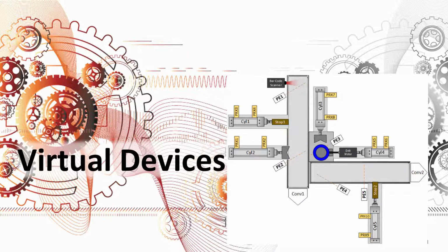Well, if you consider that behavior, that means you energize a solenoid, and after a period of time the cylinder is either extended or retracted. And we know it's extended or retracted, either by virtue of a timeout, a done bit, if you're going to do a timer-driven sequence, or a proximity switch, Hall effect sensor, a sensor that senses that the piston has moved to the extend or the retract position.